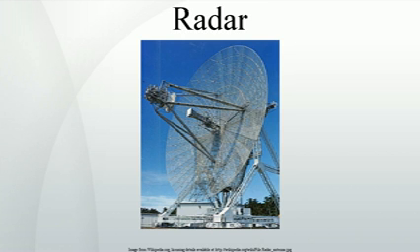Phased array interferometry or aperture synthesis techniques, using an array of separate dishes that are phased into a single effective aperture, are not typical for radar applications, although they are widely used in radio astronomy. Because of the thinned array curse, such multiple aperture arrays, when used in transmitters, result in narrow beams at the expense of reducing the total power transmitted to the target. In principle, such techniques could increase spatial resolution, but the lower power means that this is generally not effective. Aperture synthesis by post-processing motion data from a single moving source, on the other hand, is widely used in space and airborne radar systems.